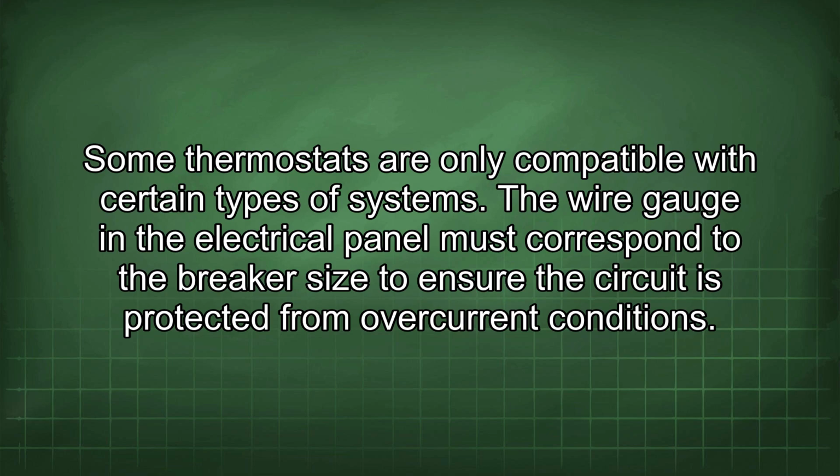The wire gauge in the electrical panel must correspond to the breaker size to ensure the circuit is protected from overcurrent conditions.